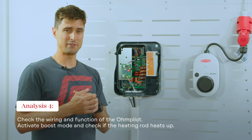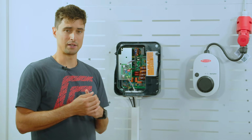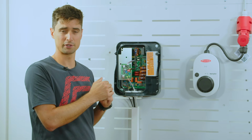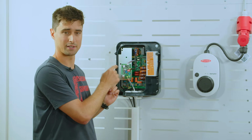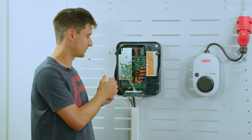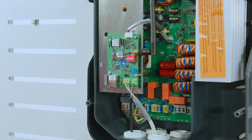For the next step, we activate the boost mode of the Ohmpilot, and we do this by pressing the touch sensor 3 times. Please note that on this print there's hardly any voltage, and you can also switch on the boost mode and touch this button while the Ohmpilot is switched on. So this is not harmful. 1, 2, 3, and boost mode is activated.